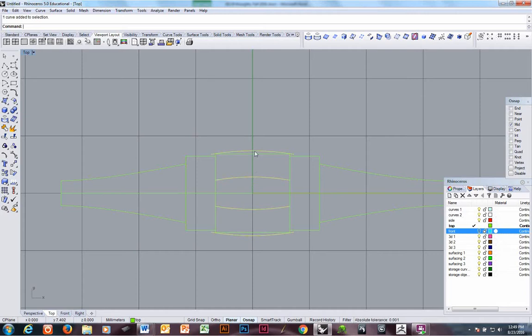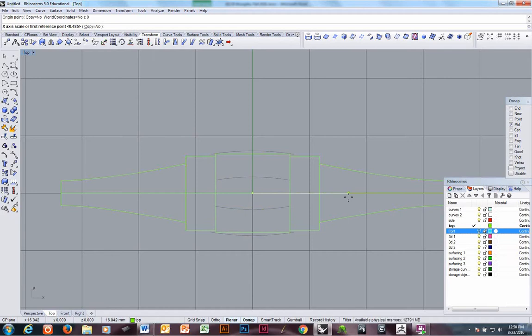I'm going to want to scale this all in, okay, until the outside matches the width, because I need the width to be this width. So, transform, non-uniform scale. I don't want any scaling here, so that's 1 for 100%. I do want scaling here. Now, I'm being kind of fussy because I did this all by eye. I don't even know what this dimension of this width is, but I might as well stay true to it. And I want no change in the Z.